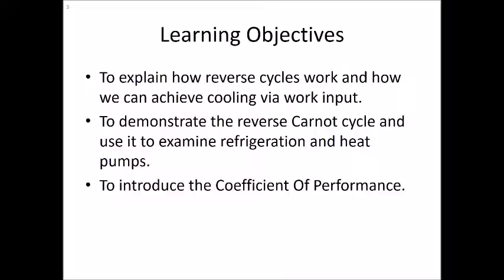And then in the third case, we'll look at this idea of a concept called coefficient of performance. Now, coefficient of performance is very important to us because this is an equivalent factor for efficiency. But the problem with COP is when you calculate it, in many cases, it can be greater than 1. It can be perhaps 4 or 5. So if the COP was 4, that's telling us that it's 400% efficient, which as engineers in training or people with common sense even, we know that you can't have something that's 400% efficient.